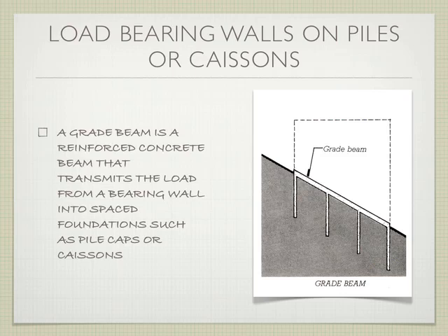So what we did is, and in this case, we didn't drive piles. We drilled very small caissons, right? And so I said the minimum size of a caisson was 18 inches. We had a few 18-inch piers. We had a lot of 12-inch piers. That was what the engineer specified. Again, it's only a 2-story building, right? So it wasn't too much weight.